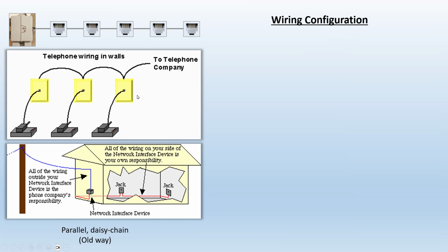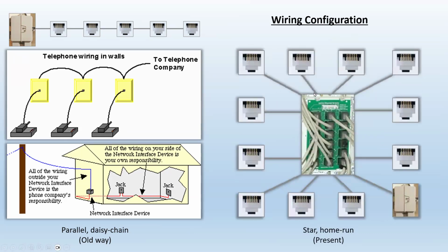Now we're not only not using a telephone wire to connect telephones, because it's a good idea to use Cat5e at least to run the signal to your telephone outlets, but we're connecting that as a star configuration, so everything home runs, and you have a little bit of a patch panel.